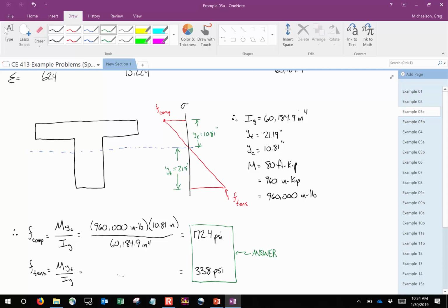To give you an example, if you're designing, let's say, a two-span bridge, okay, you've got an abutment, you've got a pier right in the middle. Well, right there over that pier, the bridge is going to want to do that. So it's undergoing negative bending. So in that region, your reinforcement and your design is different than out, say, in the main spans where it's wanting to smiley face a bit.